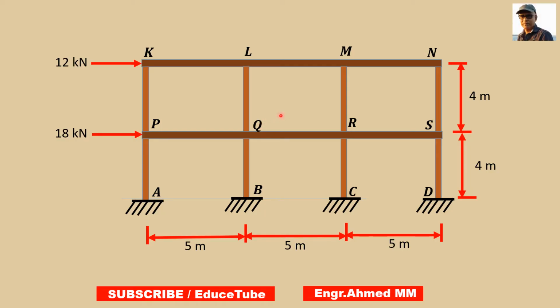First assumption: a hinge is placed at the center of each girder. How to do that? Like this. Because these hinges are assumed to be a point of zero moment. It is a very important point.